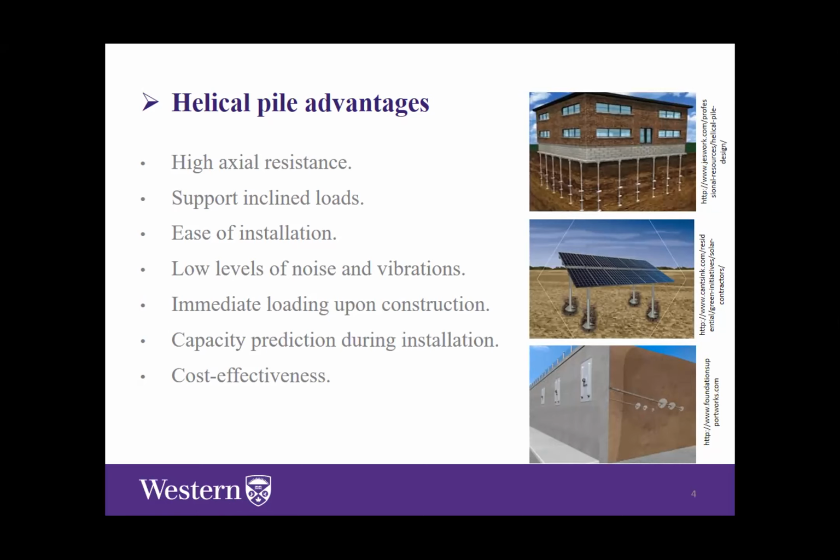So if, for example, there is a differential settlement in a building and we want to treat this problem, we can install helical piles below the footing which is excessively settled, and this will help us to solve the problem.